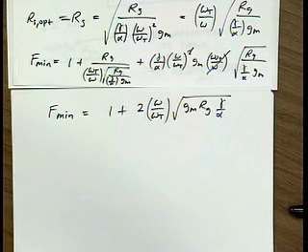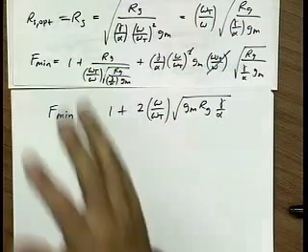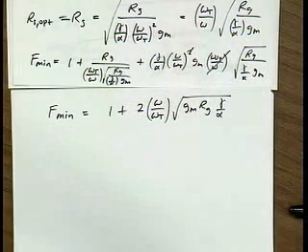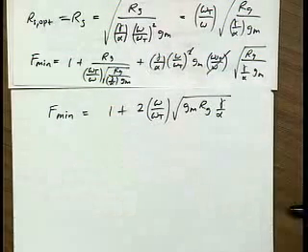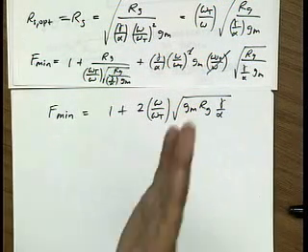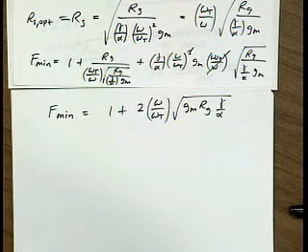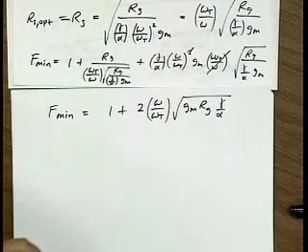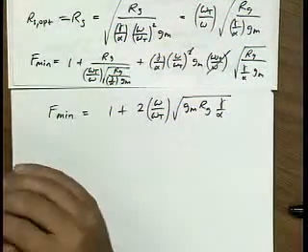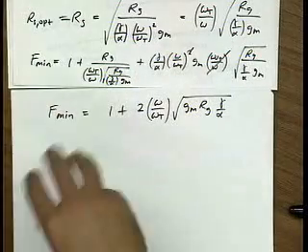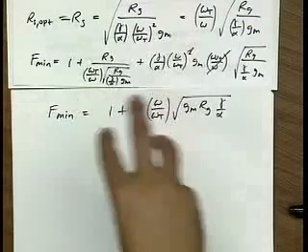Okay. So noise figure is a function of source resistance, right? Now usually for a system, when we measure it, we like to measure it with a 50 ohm source as a standard. But not all systems work with 50 ohms, right? If you're in a communication system, you use 50 ohms. If you're in, let's say, a low frequency system, you may prefer to use kilo ohms for your source resistance, right? So the concept of noise figure strictly doesn't depend on source resistance. As a concept, noise figure tells me how much my signal to noise ratio deteriorates as I go through a block, and it's independent of source resistance. Now in practice, of course, we can't live with an arbitrary source resistance. We usually are given a source resistance. It's like the antenna impedance or the filter that's driving our amplifier's impedance. But we can use impedance matching to transform it to some more optimal value. So here we're saying, what's the best source resistance to drive this amplifier that would give us the minimum noise figure? Okay?